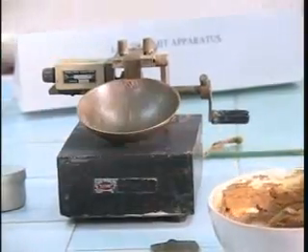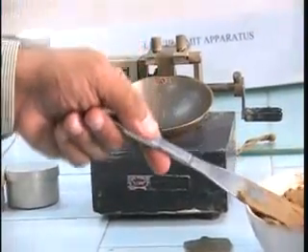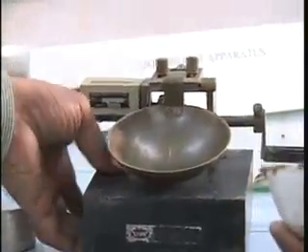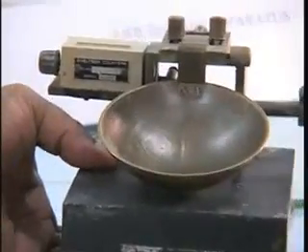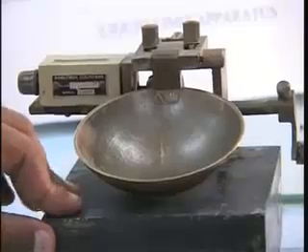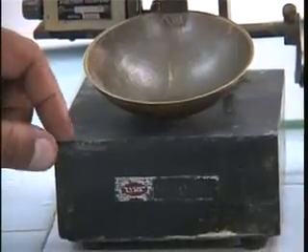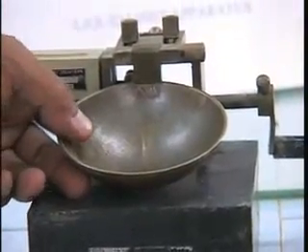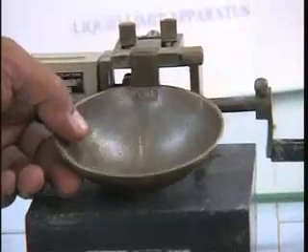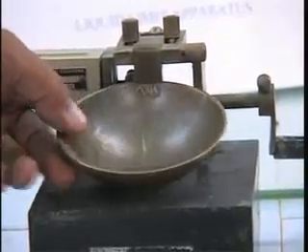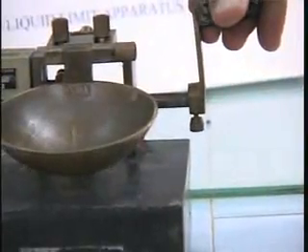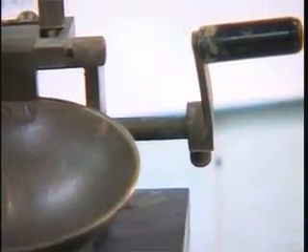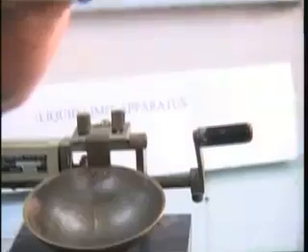What we are going to do is make a pat of this particular soil sample in this pan here. This is the Casagrande apparatus, which includes a hard rubber base, a black hard rubber base, and it has a brass pan. This pan is of standard dimension, and it has a certain standard fall, so it goes up when it is cranked up using this particular handle. It goes up a standard amount of height, and that height is given by this dimension here.